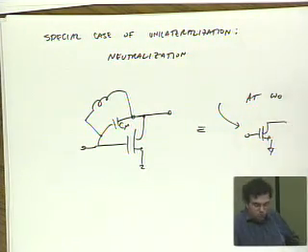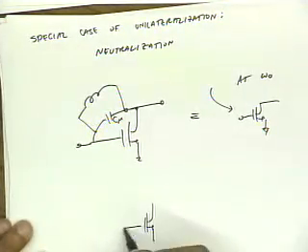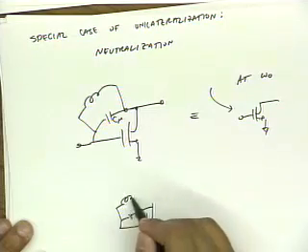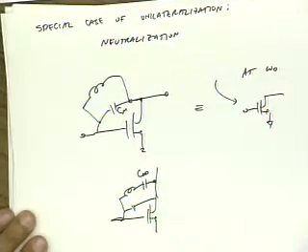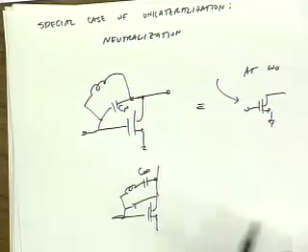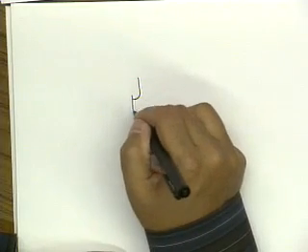And yes, there's a question? With biasing? Sure, I mean, this is an AC schematic, so the way you would do it in reality is you'd use a big capacitor here. Okay? So if I unilateralize my device, or in this case neutralize, which is easier to say than unilateralize, if I neutralize my device, then I actually do end up getting more gain out of it. This is one way of neutralizing a device, but there's a really cool way of doing it if you have differential circuits. So here's another way of looking at neutralization.